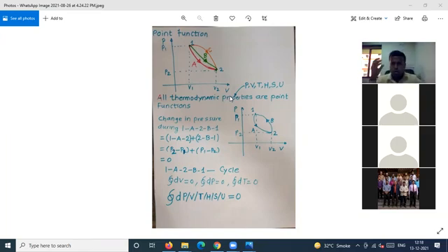Okay, so you only need to understand there are only two properties which are path functions, and those properties are work and heat. Now you understand why work is a path function, because what is the formula for work done? It is integration PdV. The formula for work done is integration PdV.